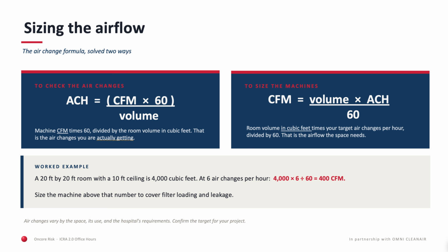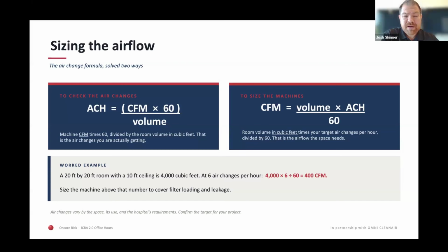Any comments about that? Well, I think you hit on a few important pieces there. My biggest comment is you talked about 6 air changes per hour. I think that's one of the biggest things that we see missed, is defining what that minimum air changes is. And at least in my experience, 6 is the minimum for sure that anybody's going to want to work with. There is no standard to my knowledge. I've seen hospitals at 10 or even 12, but I would say working with at least 6 is what everyone should strive for.